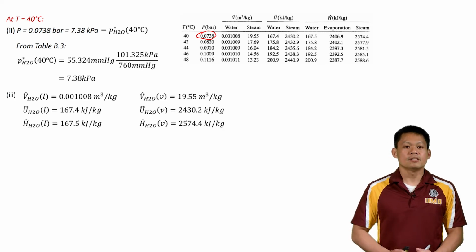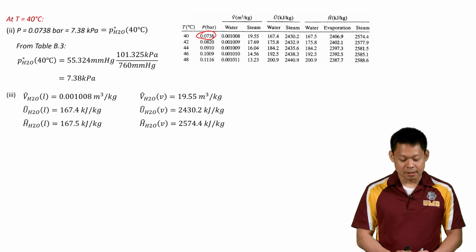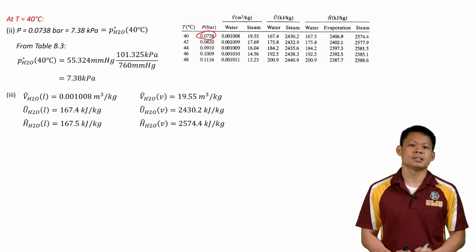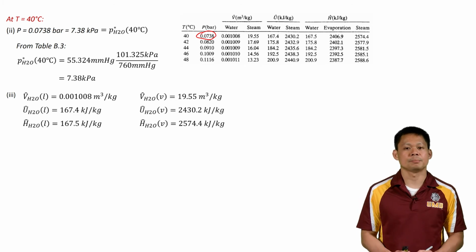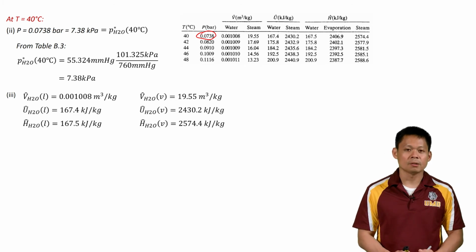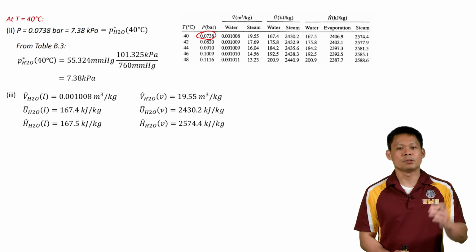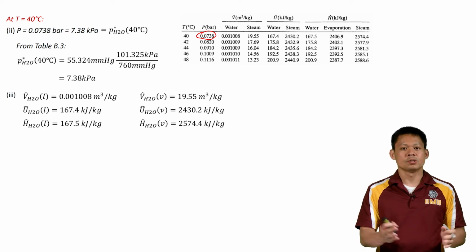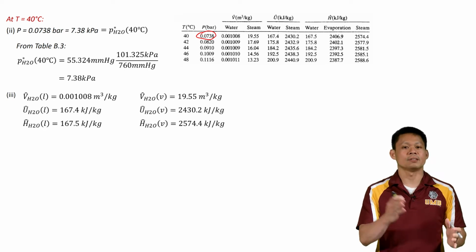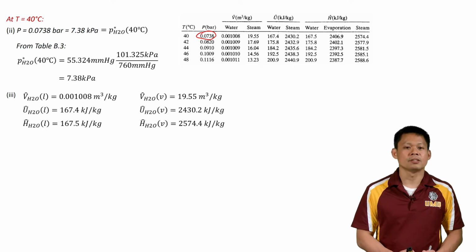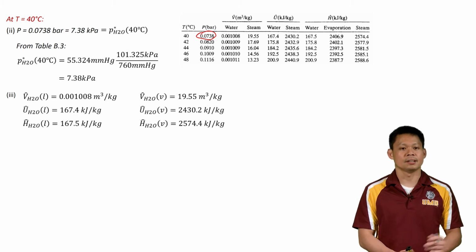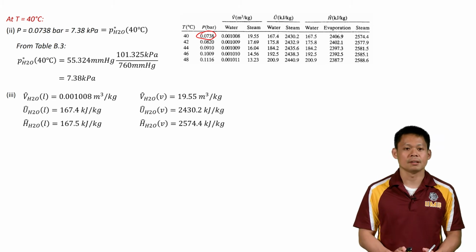All right, let's look at the three different variables that are given here. We have the specific volume, we have the specific internal energy, and the specific enthalpy. So I picked out all the values they give you for both water and for steam. So you can either have saturated liquid or saturated steam. Those are the different values. And let's take a look at the trends that we see. What are the differences between these values in the liquid phase and in the vapor phase?